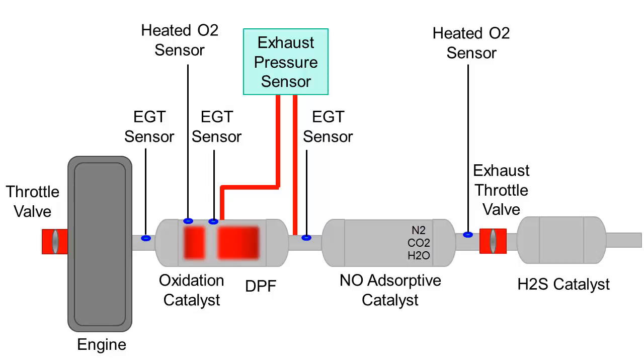The upstream oxygen sensor is monitored to achieve the right oxygen level in the system. The post-converter oxygen sensor is also monitored, and changes in the downstream oxygen level will signal completion. The frequency will depend on operating conditions, but an example might be 12 times per 1,000 kilometers.